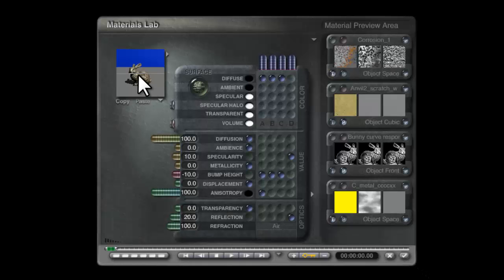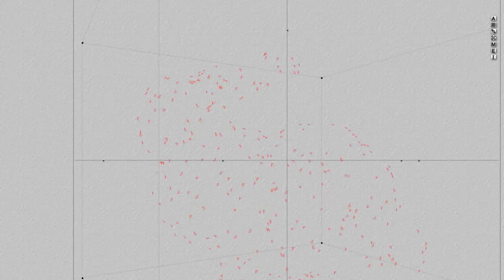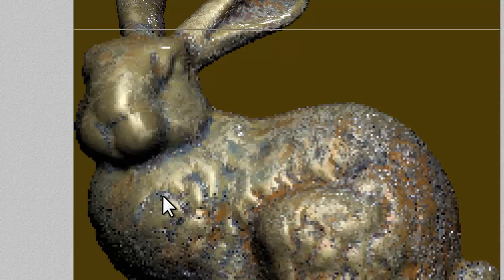Okay. Now I've got the choice now whether, you see, the reflection is going to be a bit too strong, as I was saying, because of the going fully white, but it'd probably be okay for the material transitions. So I've got reflection controlled with the original curvature, which probably won't show up, but the material transitions, which showed up very badly, and the transition for the bump height between the material, are now under the control of this image that's been generated from a map of the surface. So let's see if that looks any better.